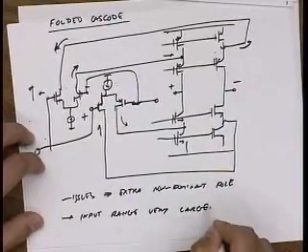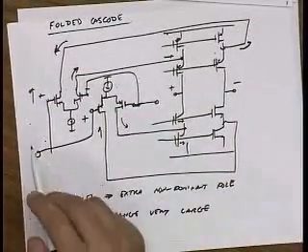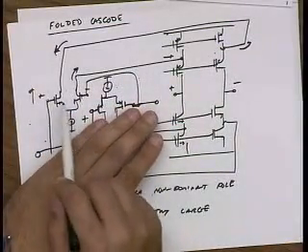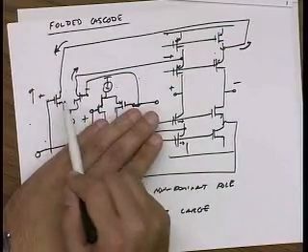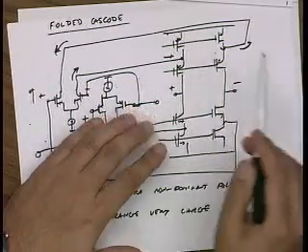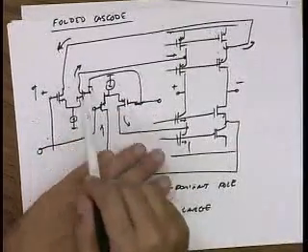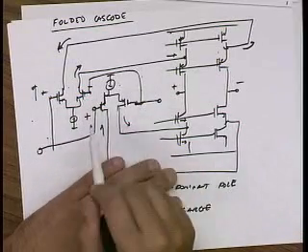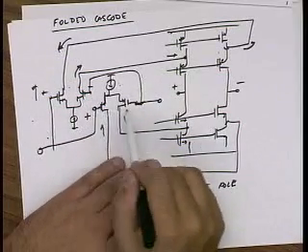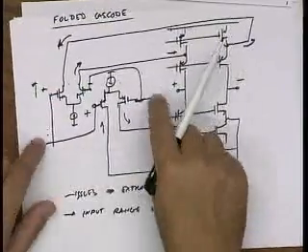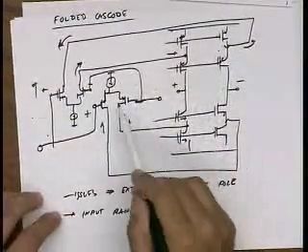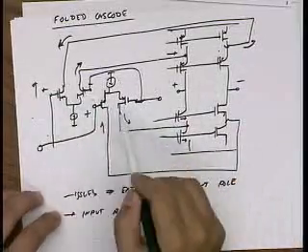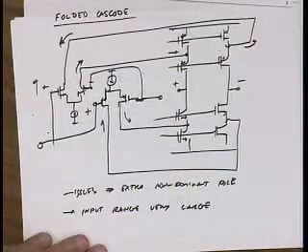So the idea is that normally if I just got rid of one of these guys, if the input goes positive, that's great. If it goes negative, this guy just shuts off, right? And the amplifier stops functioning. So my input common mode range on the low side is limited by this guy. But now, if I actually add a PMOS stage, it's the opposite. As the input common mode gets low, this PMOS stage is happy and continues to function very well. So now I have a large input range over which both devices are active, right?